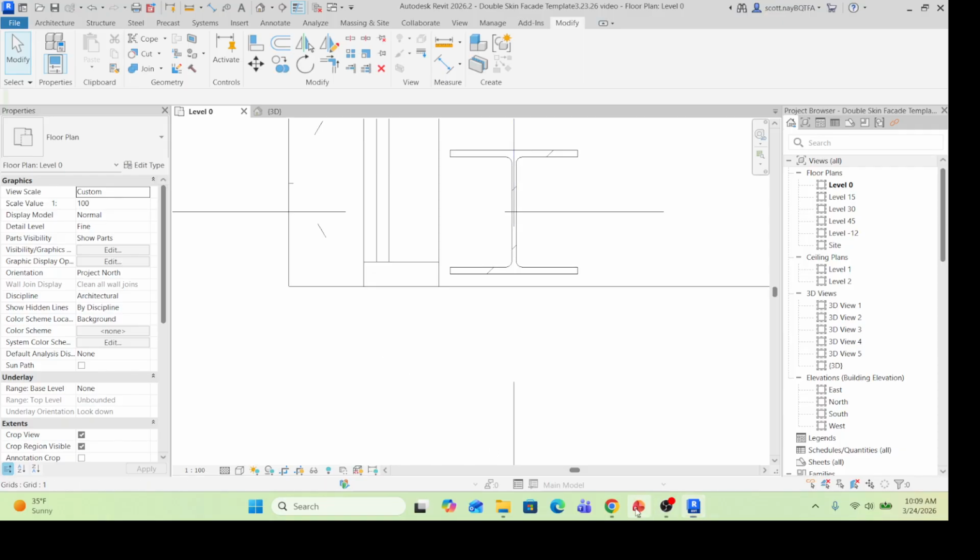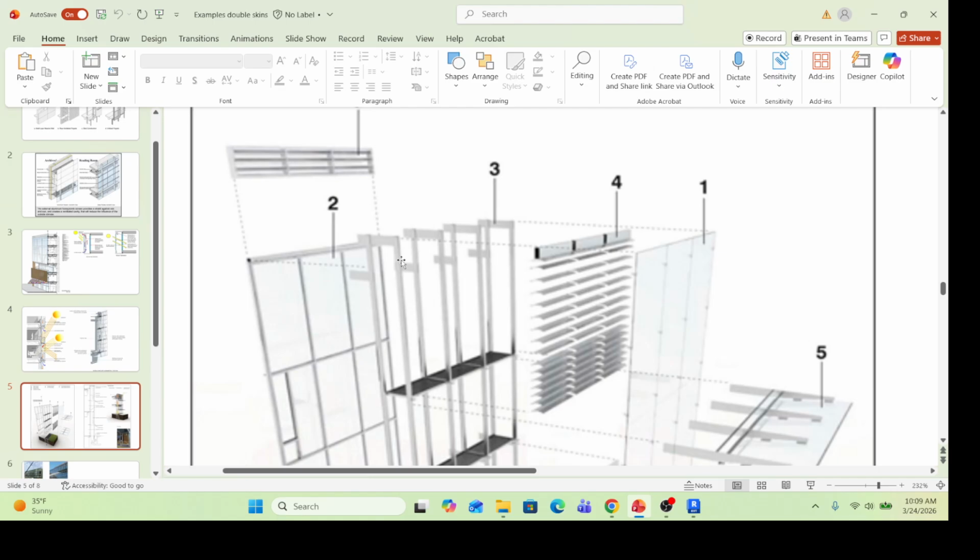And so my frame, if we look at this thing here, this is 4 inches. So that's 8 plus 18. And then the mullions I made for my custom one, that'd be out here, were 4 inches. So I need a reference line that's far enough away from the edge. And unlike the first one where it's drawing from the center line, because we're placing it on the mass, we don't do half of the mullion, we do the full one.